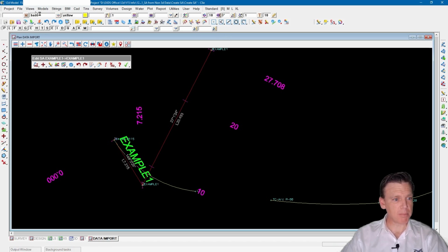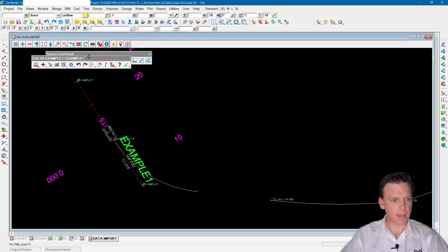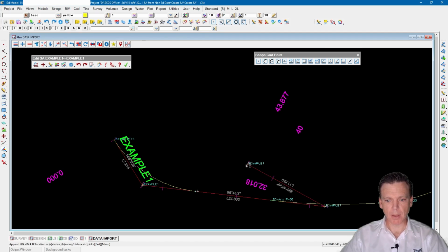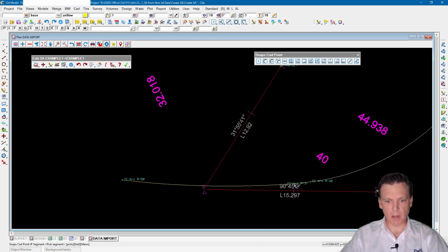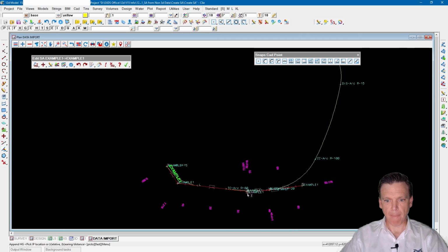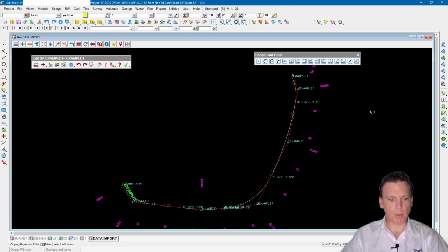Now, because I've got a number of snaps to do, again, you might come back to the toolbar. They're in alphabetical order, so if you just click in there and hit S, it'll go down to the top of the S list, and I'm after the CAD points because I'm going to be using the CAD interval one quite a bit, so the snaps IP one quite a bit. So I'm going to go to this IP, around the corner again, to this IP, to this IP, this one, and finishing there. Escape. So there are all the IP points now locked in.